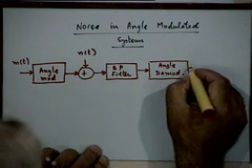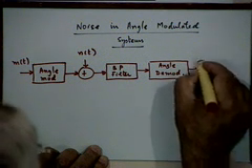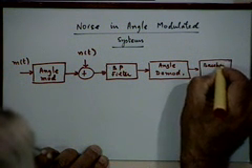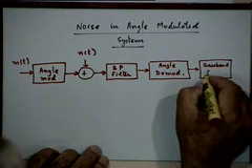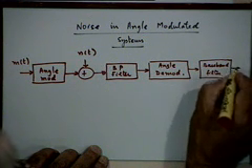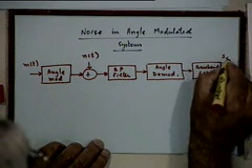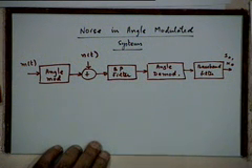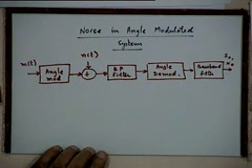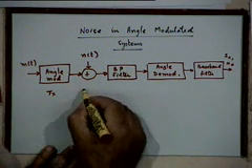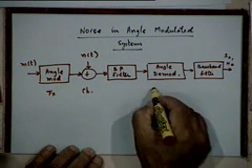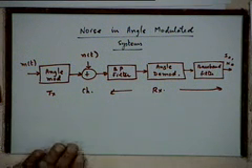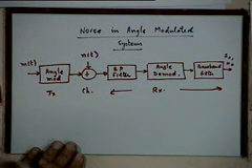Okay. And finally, you will have a baseband filter whose bandwidth is the same as that of the message signal. And you are interested in calculating your output SNR by calculating the output signal power and the output noise power. So, that is your transmitter, that is your channel, this is your receiver, and that is your model which you have to use for doing your SNR calculation.